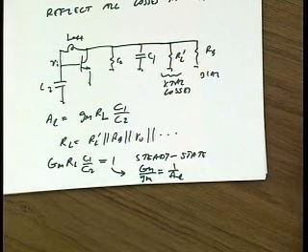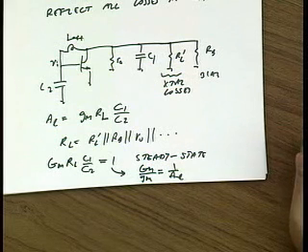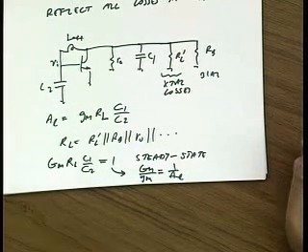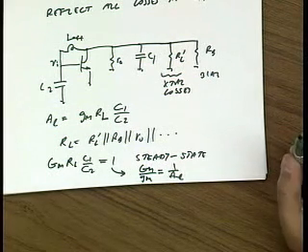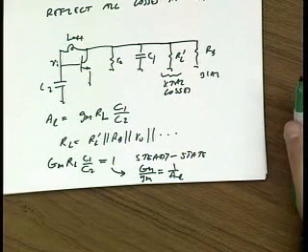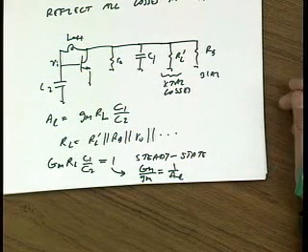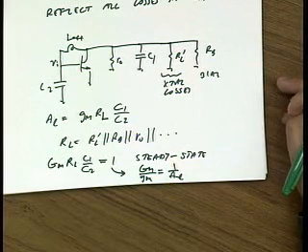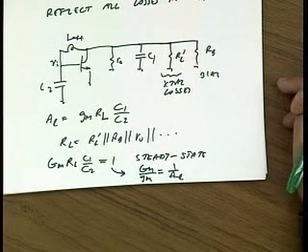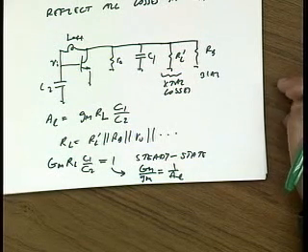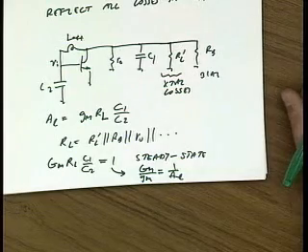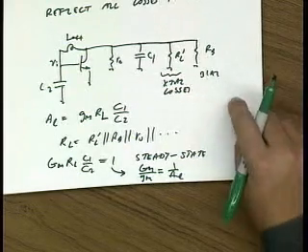Any questions about designing crystal oscillators? Of course. No, I was just wondering, so if I intentionally want to oscillate on an overtone or on a higher order frequency, I can design my loop somehow that I get a loop gain lower than 1 at the fundamental and higher than 1 at the overtone? That is definitely possible. And it's a little bit difficult with the Pierce.